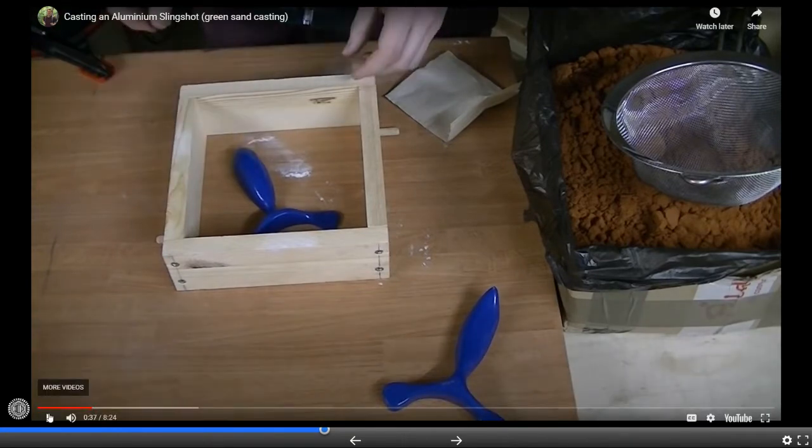Then, I'm just going to comment here real quickly. You can see that your pattern is actually set into two, and most of the diagrams I showed you had patterns that could break up. So the first part of the pattern, they put in one part of the mold. Second part of the pattern, they put in the other part of the mold. Remember, these are called cope and drag. Okay, so now we'll keep going.